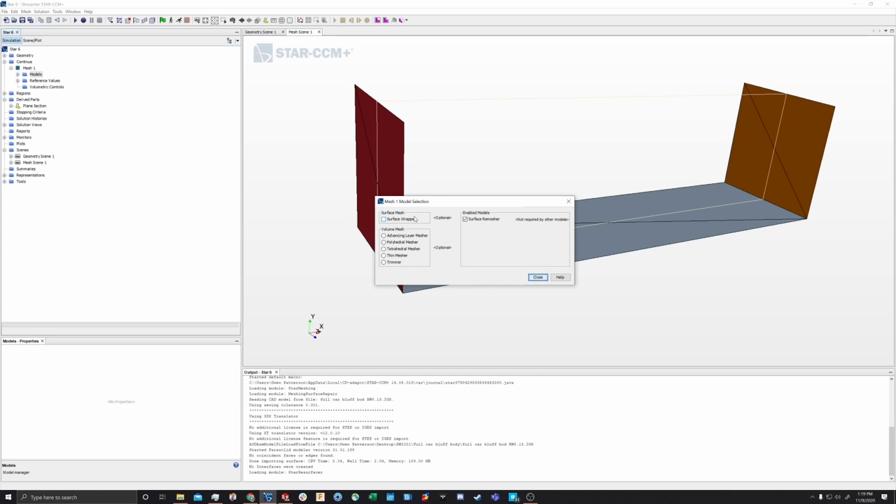One of the main issues though is it may fill holes that you actually wanted. So for example, on our multi-element wings, it'll often connect two of those elements, and we really don't want that. That ruins our airflow. So we generally don't use this unless we've got an issue. We think it might help, but it kind of ups the computational intensity quite a bit. So if you don't have to use it, you shouldn't. I wouldn't recommend it.